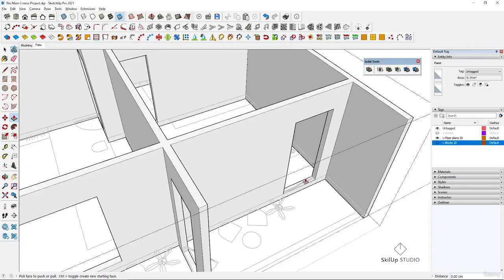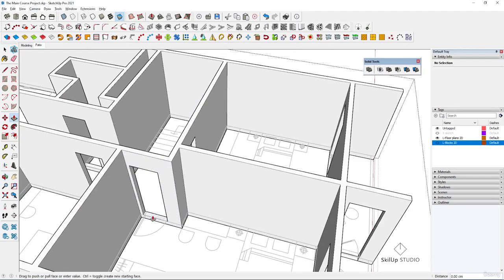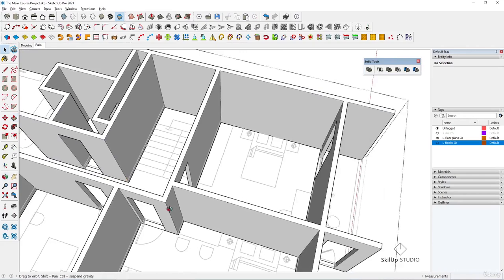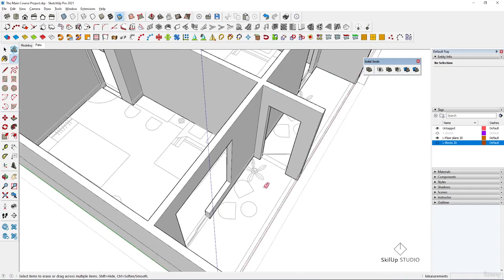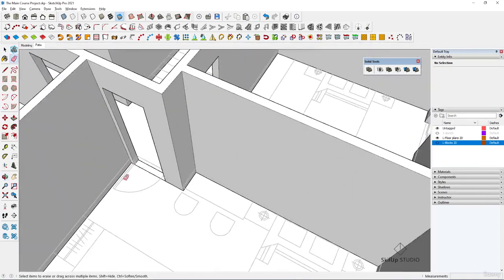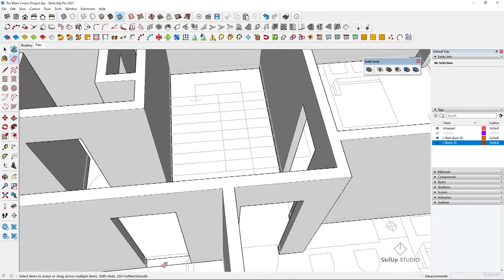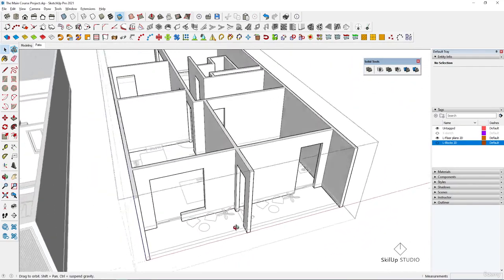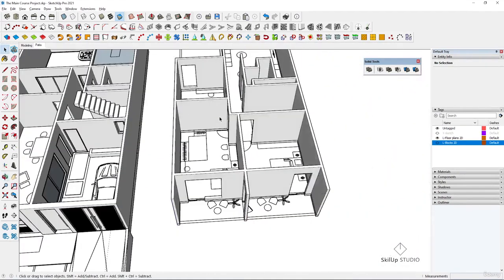We will push down this part, double click with push tool. It will remember how much we went down, and it's equal in all parts. Thus we have finished these parts. We will use eraser tool to erase these lines. After we finished the cleaning of the door openings, so openings became clear to us, we exit this group.